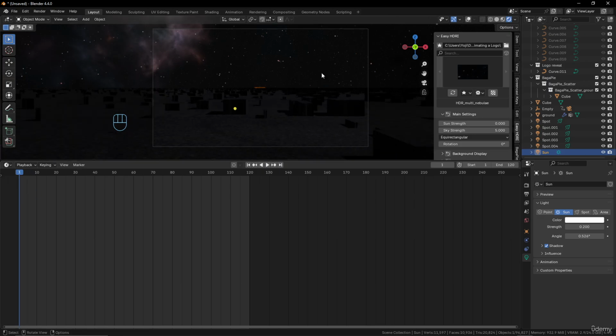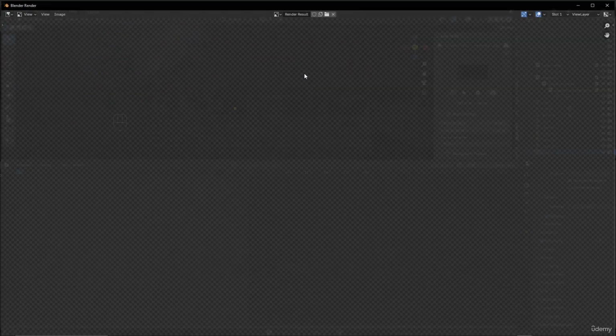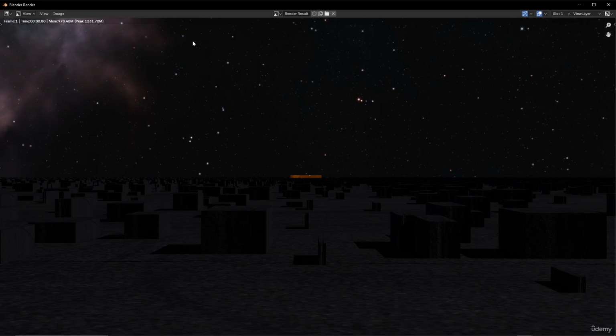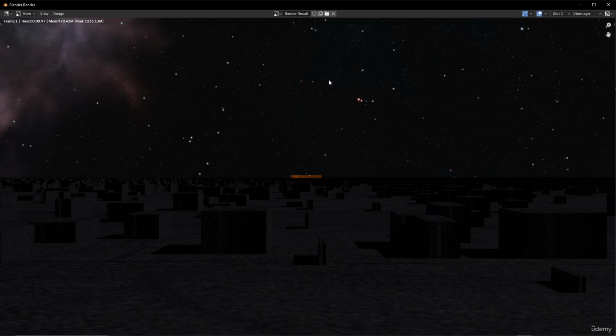And what we can do as well is add a little motion blur here. If you use the motion blur, it will increase your render time. So without motion blur, one image with F12, for example, okay, it's not even 1 second, so very quick. But if you add the motion blur here, it will multiply your render time.